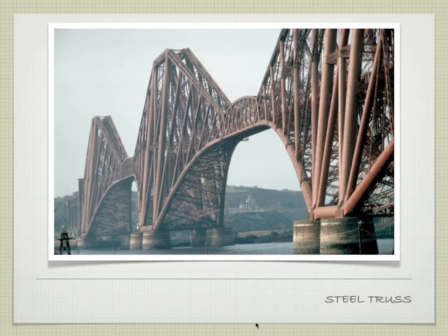The key on a truss is making sure that the elements are triangulated. I'm going to draw for just a second to help illustrate this, certainly because you're going to be making trusses anyway. The idea behind a truss is that we're taking something that would typically be a beam. Let's pretend this is a beam, you can imagine it as an I-beam. We take the web out and leave what's called the top chord and the bottom chord in the same configuration. So this is a top chord, and this is a bottom chord. We want those to stay consistent.